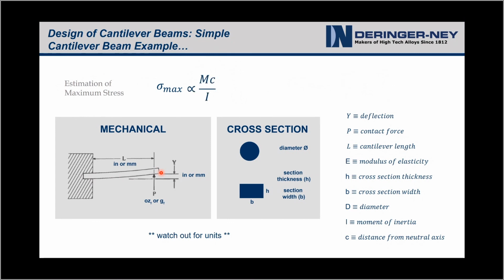From the mechanical standpoint, that's frequently derived by looking at the moment of inertia, the moment, and the neutral axis. This is the process that's followed in many mechanics texts, where we reduce this to understand the load, and the length gives you the moment. Then you substitute I in for the moment of inertia. I've just added proportionalities because I've taken out some of the factors.